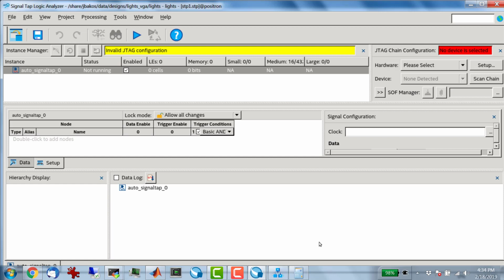So generally, the first thing you set up is the clock. The way this works is that when you're monitoring signals on the FPGA, there's not enough bandwidth in JTAG to read them in real time. So instead, you set up these buffers on the FPGA that start recording the data whenever a trigger event happens that you set up, and then when the buffer fills, it sends the data back over to your host, and it puts it into a timing diagram.